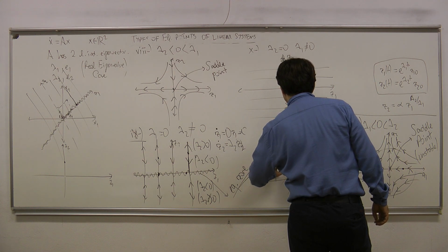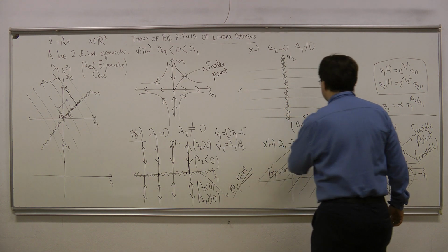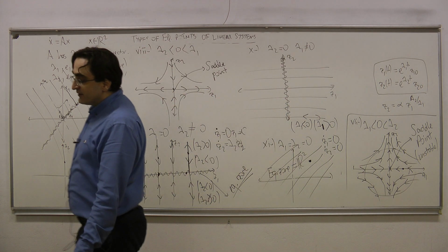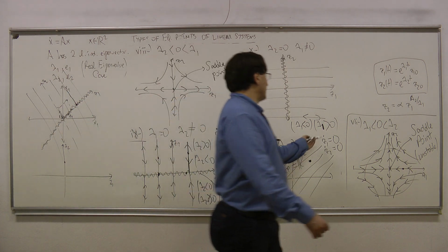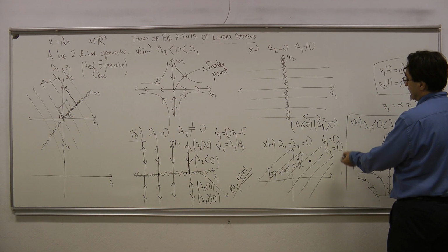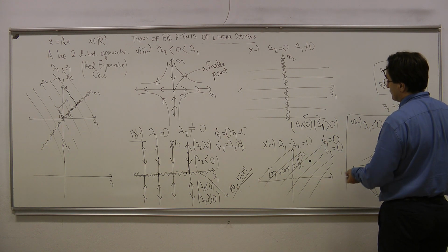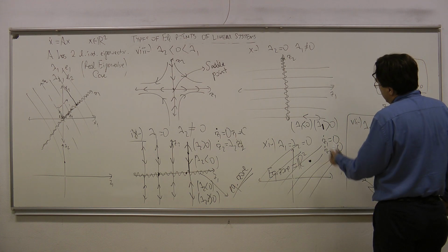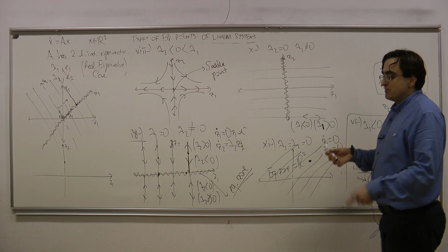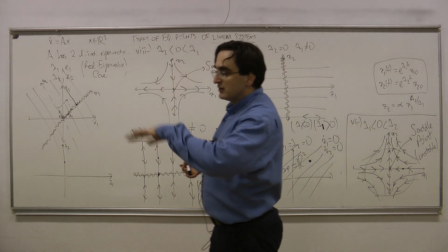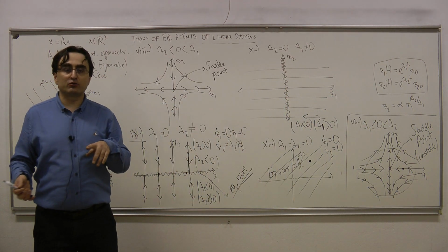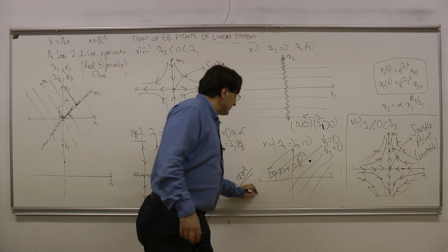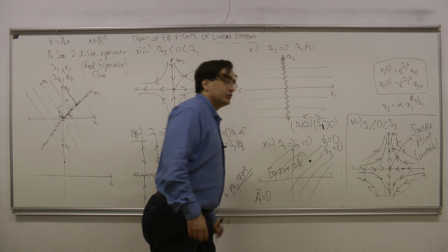So we see that the equilibrium zone is nothing but the whole state space R2. Why is that? Because look at the equations. The right-hand sides are both equal to 0, so there are no constraints on Z1 or Z2 for an equilibrium point. Okay? And here you can also say that, remember, the matrix A bar is a diagonal matrix which contains the eigenvalues on the main diagonal. But if both of the eigenvalues are 0, then A bar is going to be equal to the 0 matrix,